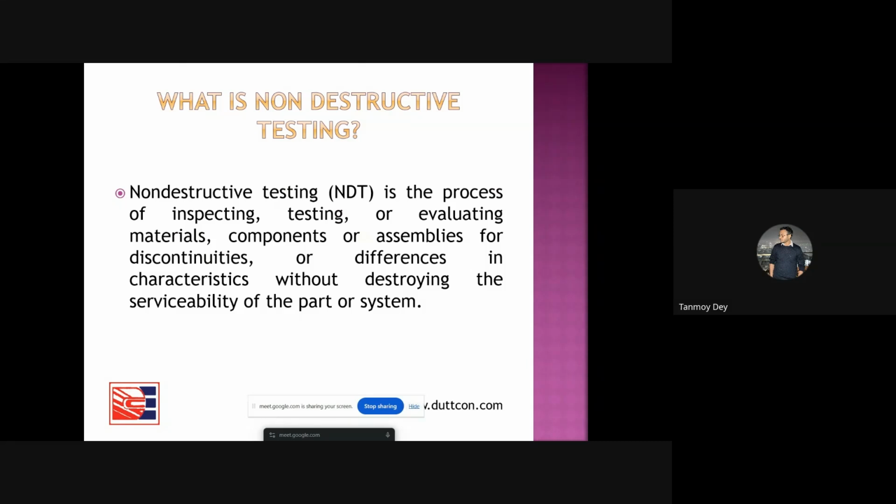So NDT is widely used in civil structures, RCC structures, as well as load-bearing structures. We can conduct this, though we are very much accustomed to NDT of RCC and steel structures. To restore heritage buildings, load-bearing buildings also have to be tested. The brick strength and mortar strength are tested through a pendulum hammer and similar methods.